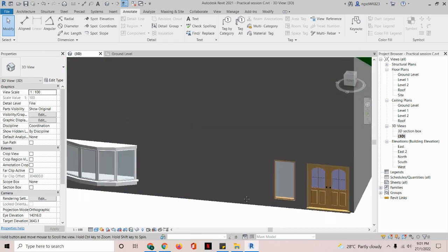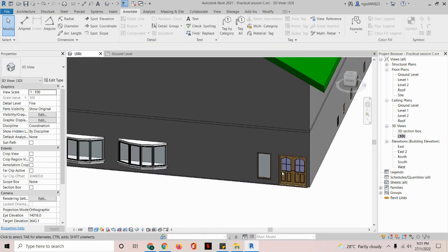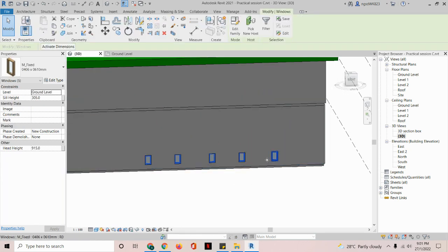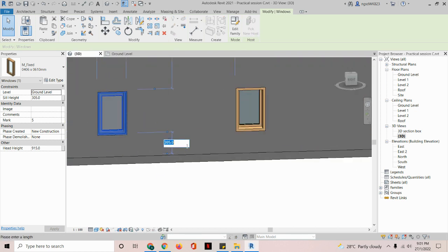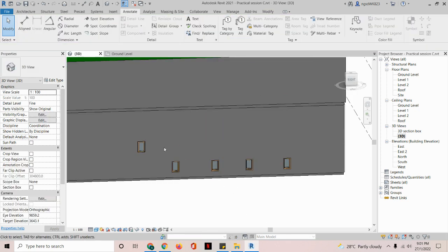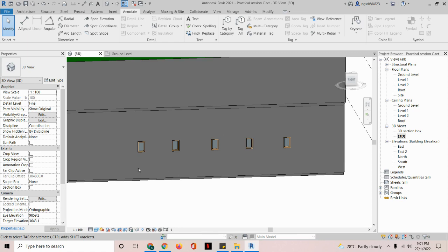Okay, so here is looking all right. Here, this also looks all right. If we look down to here, let's say the window that we created is too low. Actually we can change the height either by clicking on it and modifying the height directly here. Let's say I want this to be at least 1.5 meters. I change it, and it will be up here. For the remaining ones, we can just change them over here also, and all of them will move up.